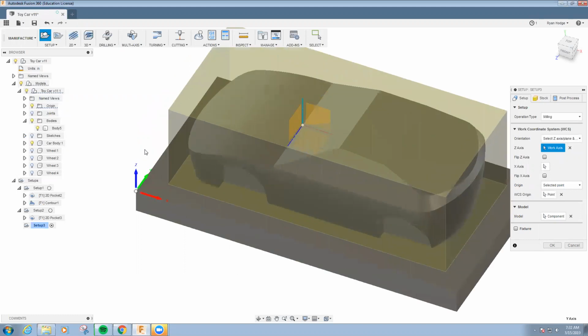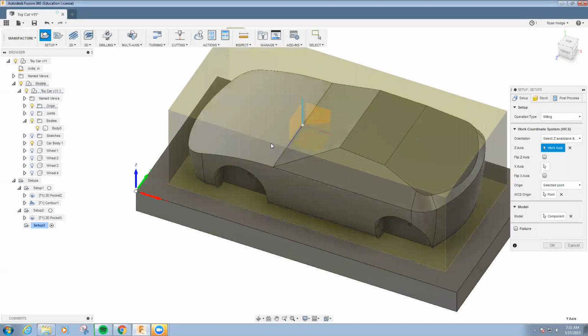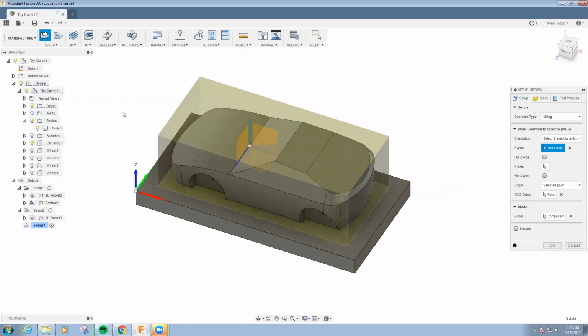Okay. So now we have to maintain our origin from the same spot because that's the reference of how the machine locates the dowels. So it's critical that this be our origin. But that could be an issue for our tool touch off. So that is not going to work.